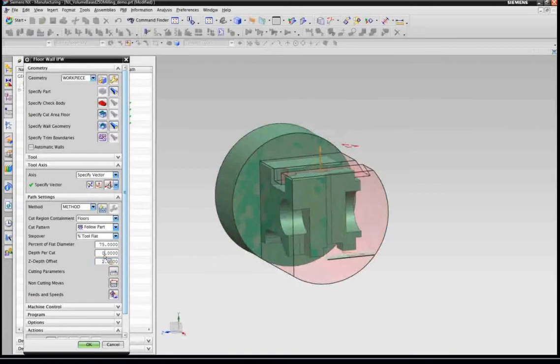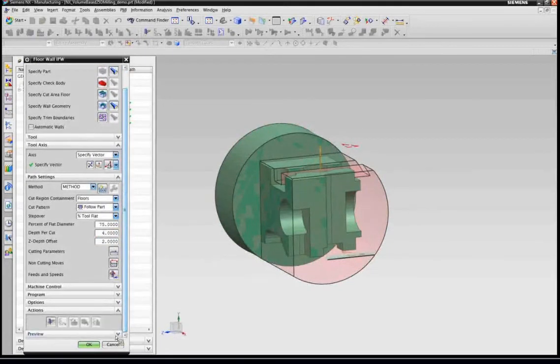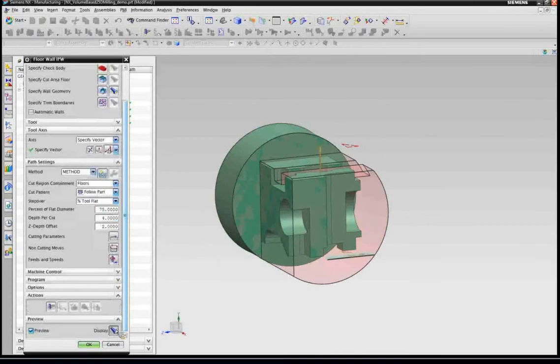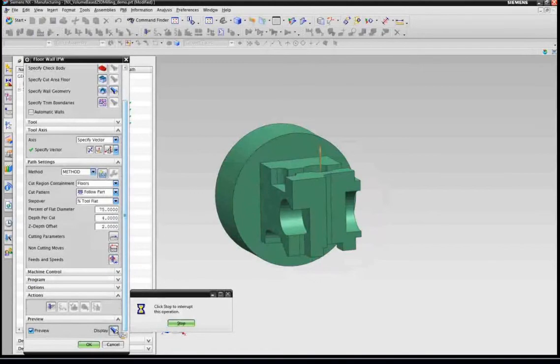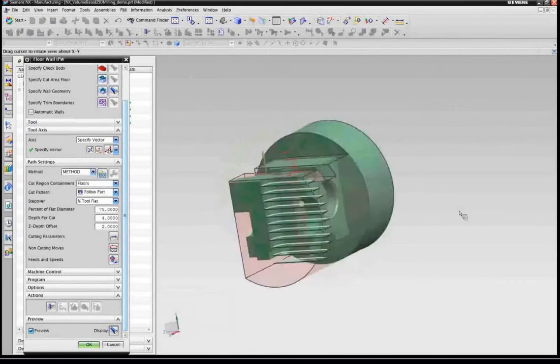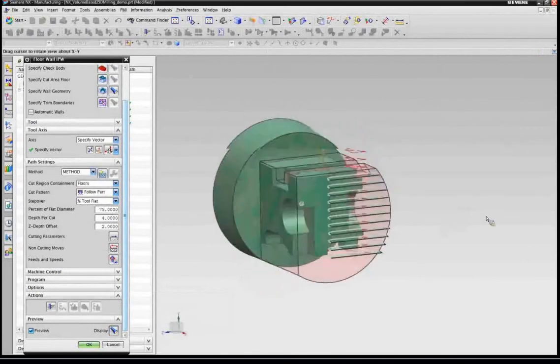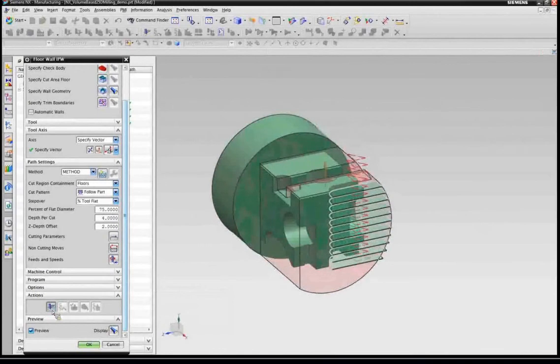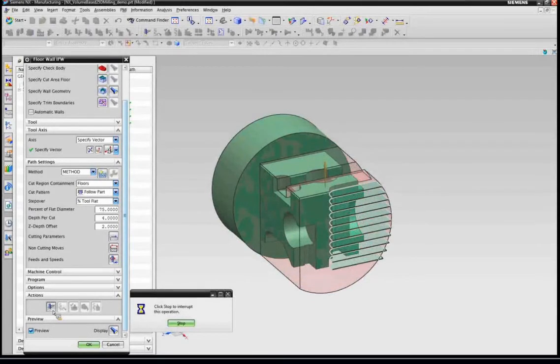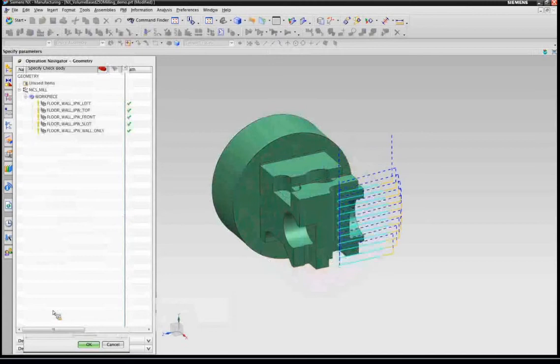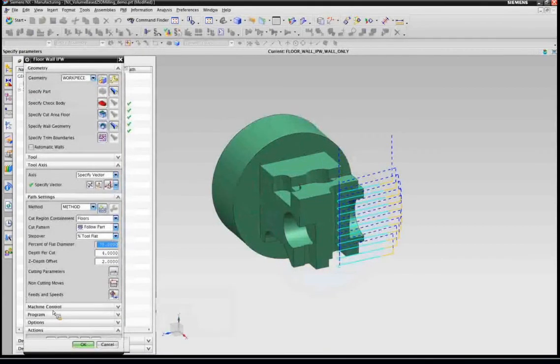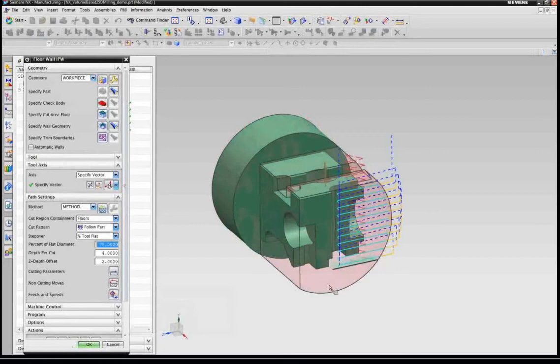And finally, let me input the depth of cut and show you the preview at the various cut levels. And you will see that, again, we're looking at the exact state of the in-process workpiece at each cut level, and that's the area we're going to cut, not more. If I generate the toolpath, I'll have a very efficient path that approaches at the right position, does a single pass, and removes that material.